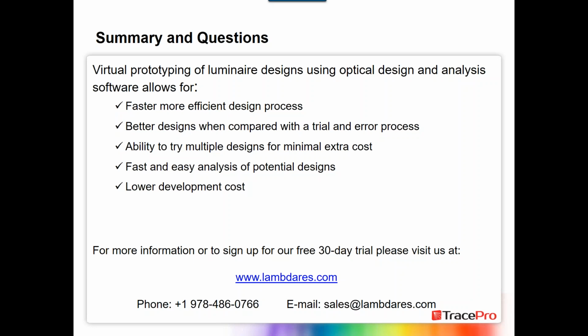I got another question for you, Dave. Is TracePro suitable for design of lenses and regular refractive optics like ZMAX? It could be. What it lacks is the optimization or merit function tools, things like MTF, spot diagrams, aberration analysis, that type of stuff. For that, at least in our suite of software, we usually recommend Oslo.